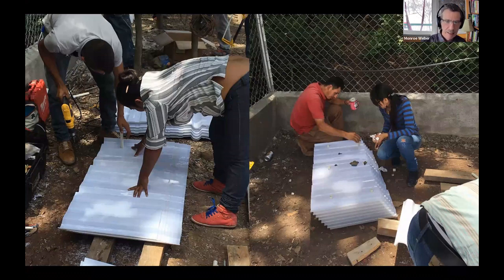Here they're making the plate settlers. The plate settlers are made with polycarbonate sheets that are normally used as a transparent roofing material. The sheets are about 1 millimeter in thickness, and then they're spaced apart using a system of pipes. So there's a 1/2-inch PVC pipe that goes the whole way through a bunch of sheets. And then there's a set of 3/4-inch PVC spacers that fit over the 1/2-inch pipe and that create the space between the plates.